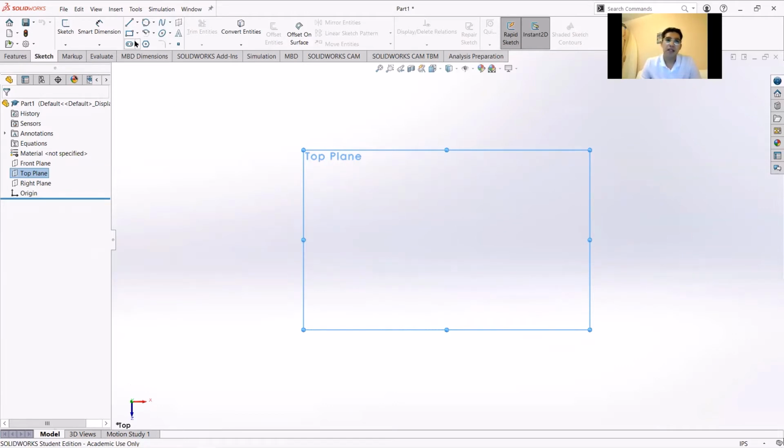So once you've selected that, we're going to go over here on the right. This is a sketch. So we're just going to click that, and with sketch, that's when your origin will pop up. And for the most part, we're going to want to keep our origins in the center of our parts, almost always, because it'll make things a lot easier. And if anything breaks, as things may later in the workshop, especially when we're talking about assembly, it'll probably be because of where your origins are and how they're mated and how they are in relation to other parts. So that's kind of why that's important.